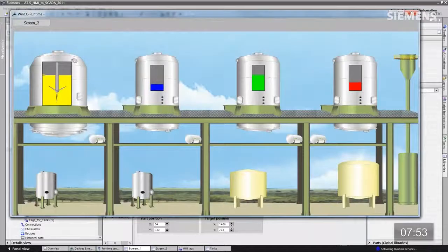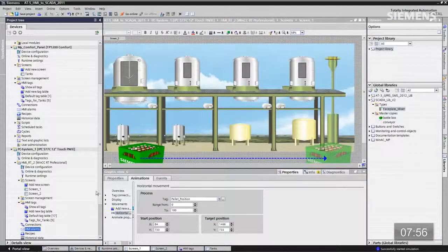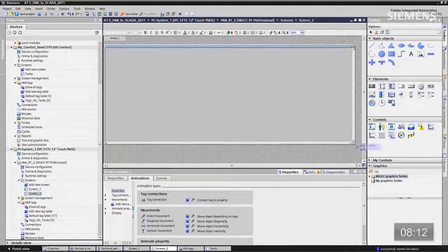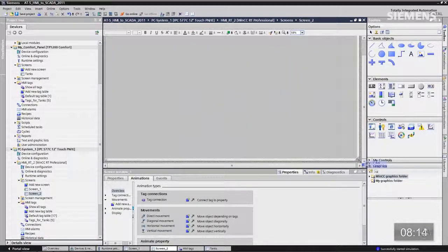However, there's one other thing I want to show you. How about actually doing a screen-in-screen or pop-up technology? So let's go to screen 2 real quick. Double click on it, and let's go grab the control icon for this. It's called Screen Window. Let's drag it on. This is the ActiveX control. You can see little alignment bars just like in PowerPoint. That way you can align your boxes wherever you want to and get everything sized right. Let's resize, refit them onto the screen.